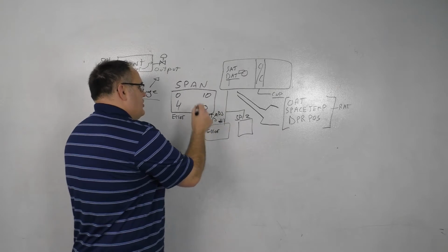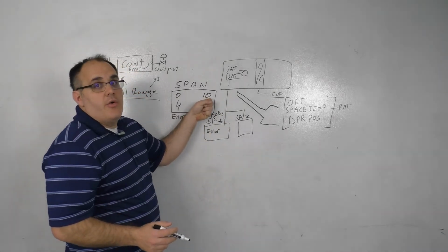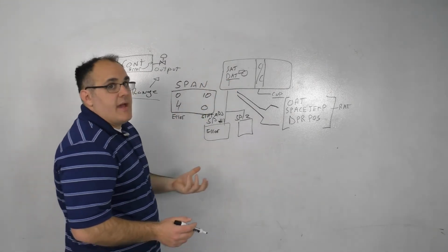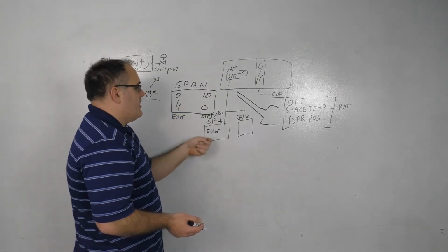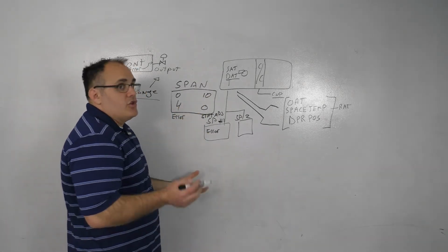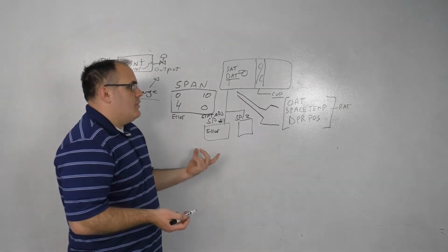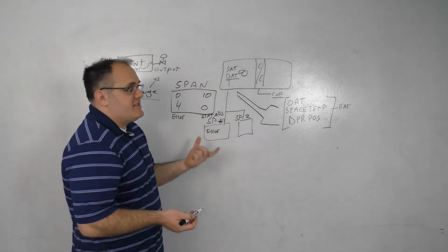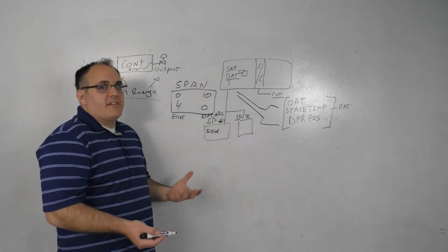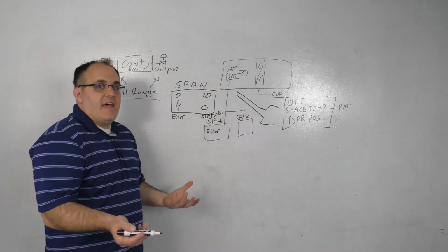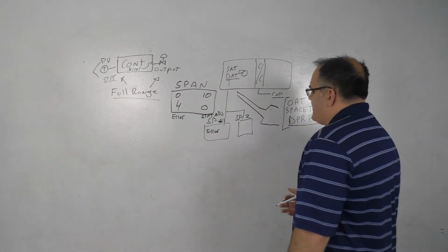What we're going to do is, as our error gets lower, we are going to raise the discharge air temp. So we would take maybe 55 degrees and add 10 to it. But if we have a 4 degree or greater error, then we have our regular 55 degree discharge air. Like I said, I don't necessarily recommend using space temp or return air temp because there could be other factors leading to that issue. What I like to do is drive it off of damper position.